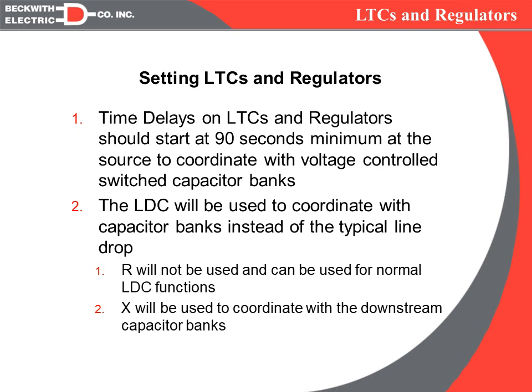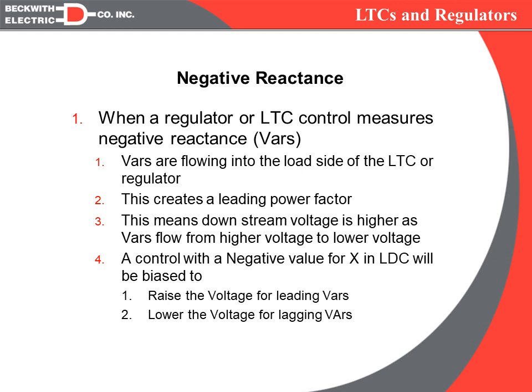But the X is going to be used, but we're going to have what we call a negative reactance setting. So first of all, what is negative reactance? Well, if the regulator or LTC control sees negative VARs, what that means is VARs are flowing into the load side of that regulator or the LTC instead of flowing out of the load side, which is another way of saying you have leading VARs.